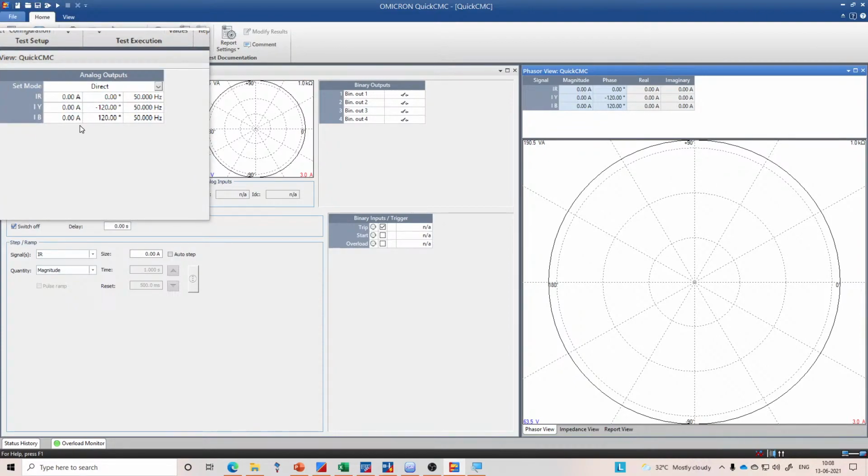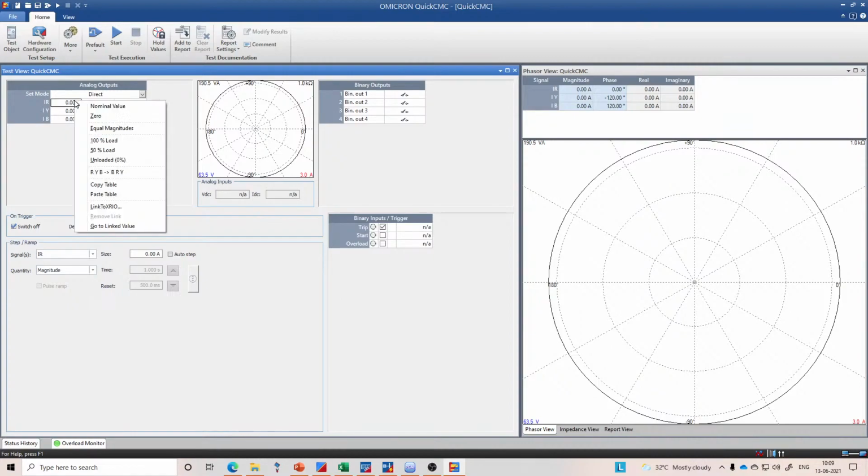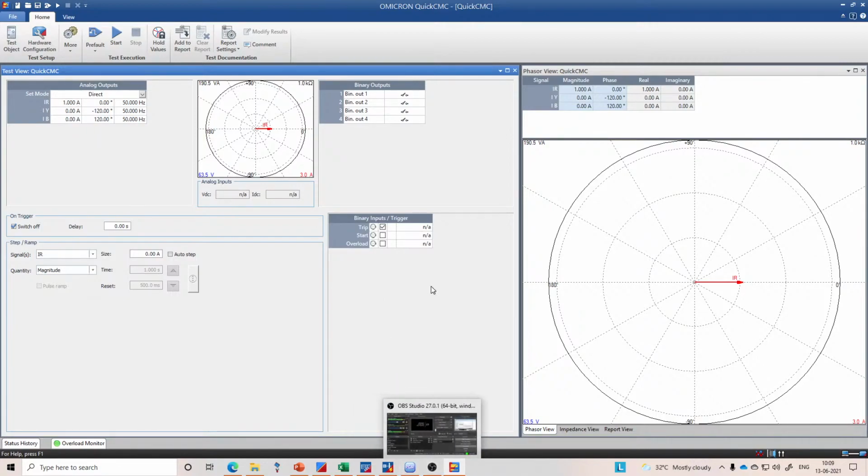So the next thing that I want to do is perform a measurements check. The first thing that we do whenever we do relay testing is we perform a measurement or a wiring check to ensure that the phases are connected correctly and there is no open circuit or overload condition existing anywhere in the system. Okay. So for that, I am just going to inject a value of 1 amp, and if I want, I can measure it or view it from the CMC itself.